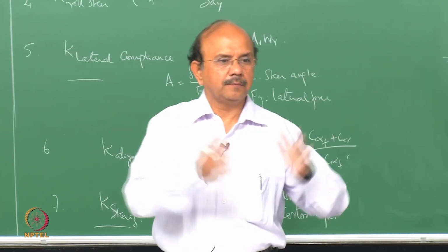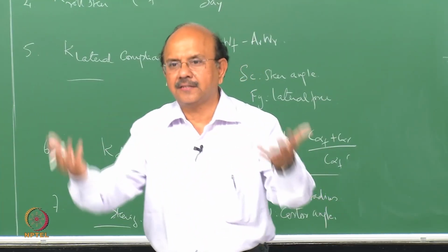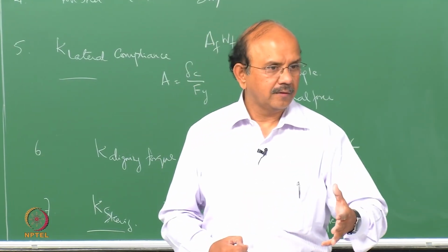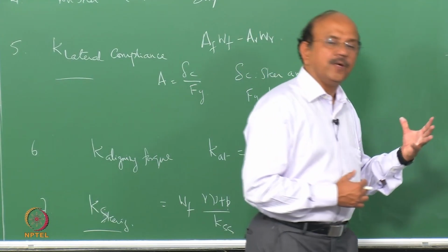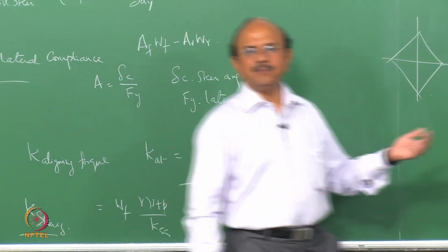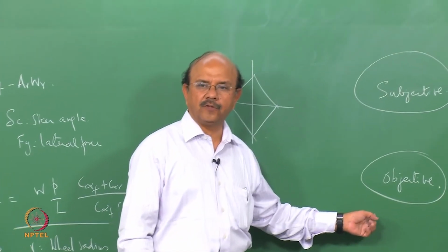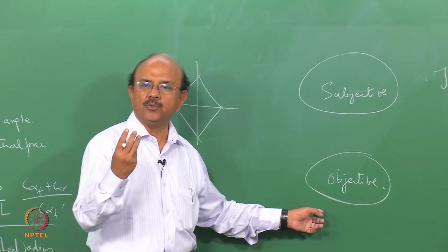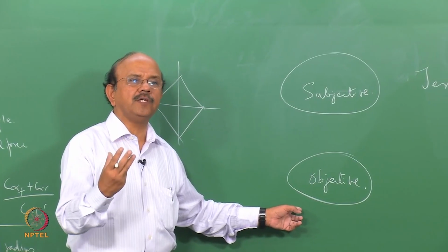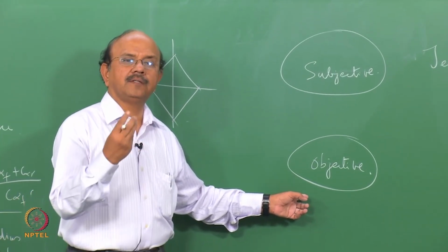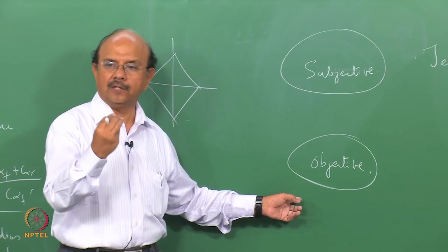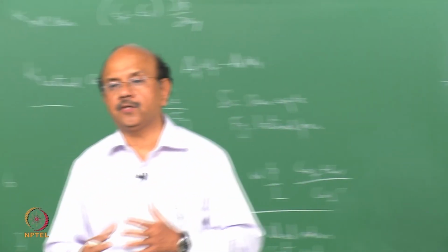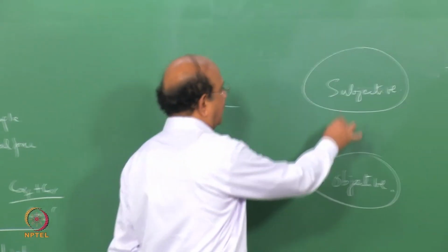So your rate gain at, say, 0.4 hertz or 0.7 hertz and so on become important. So objective evaluation is many times, most of the times, in the frequency domain, and one or two in the time domain. They are values which can be derived, measured from the car, a quantitative value which can be measured. That is the objective rating. So the whole idea in subjective-objective evaluation is to look at that correlation.